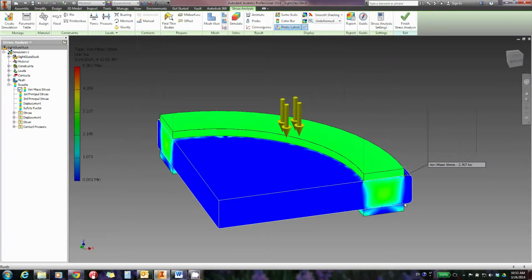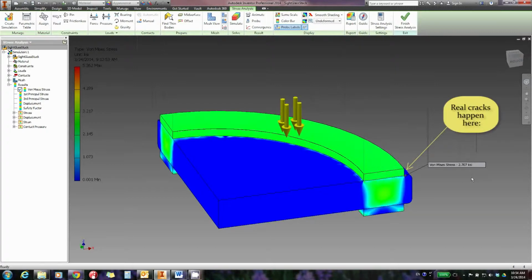And this is where safety factor claims are made, at this relatively unloaded center. But you can also easily tell that the peak loads are not here, but below the gaskets. The place that's most likely to develop cracks is right here in the neighborhood of where this arrow is. In fact, the only fracture damage I had ever seen had been in this area. And even if you are not into stress mechanics, I'm sure that you can figure out that the gaskets are crushing the glass.